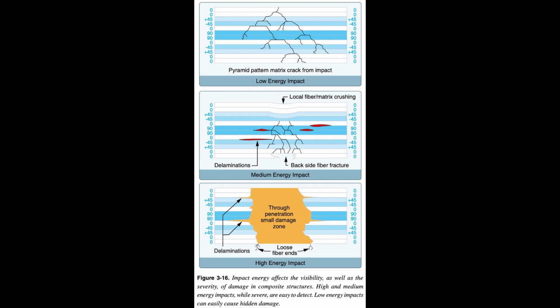The potential for heat damage to the resin is another disadvantage of using composites. While too hot depends on the particular resin system chosen, many epoxies begin to weaken over 150 degrees Fahrenheit. White paint on composites is often used to minimize this issue. For example, the bottom of a wing that is painted black facing a black asphalt ramp on a hot, sunny day can get as hot as 220 degrees Fahrenheit. The same structure, painted white, rarely exceeds 140 degrees Fahrenheit.